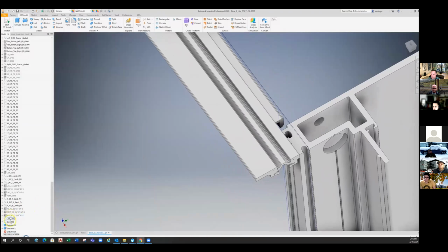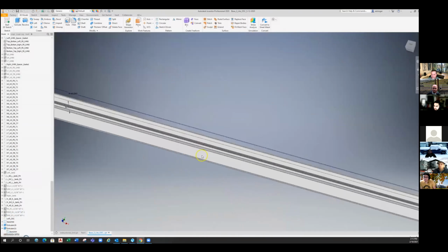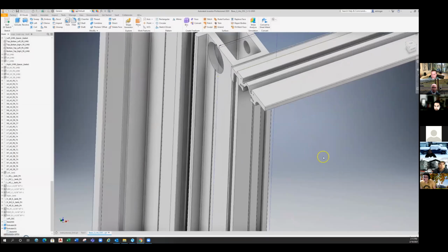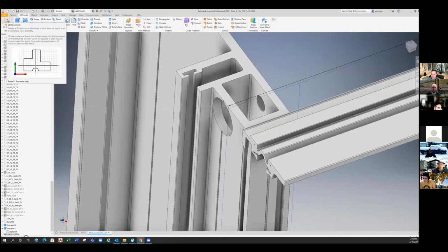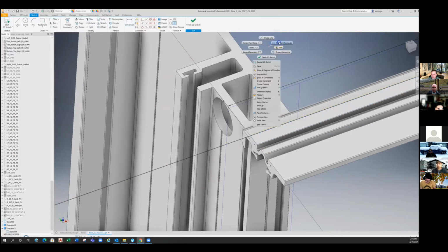When you do extrudes, your sketches get turned off. So I'm going to turn this one back on so that we can use the parameters that we used here in the next sketch on the other end of the glazing adapter. I'm just going to repeat the same procedure. So I'm going to type S for sketch, or up in the left-hand corner, start 2D sketch. Select the top of this surface.